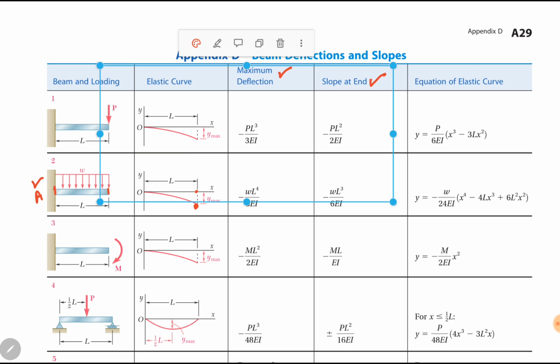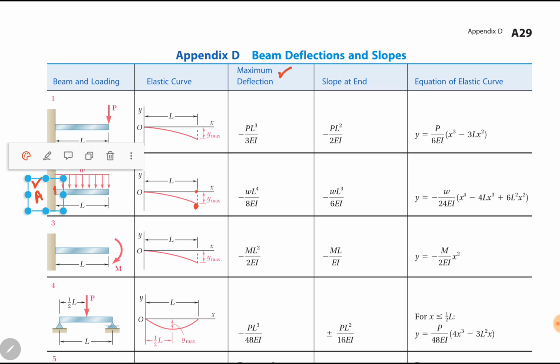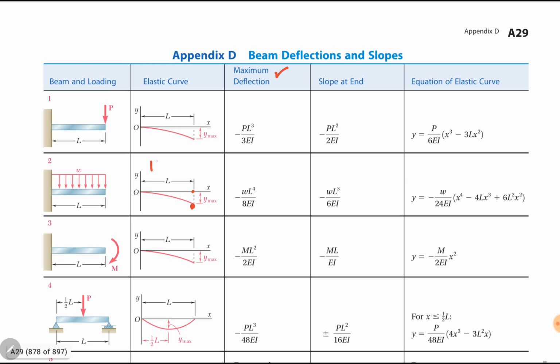Okay, I will draw a beam here of half length L by 2 and upward loading W. First remember that the given standard beam is under downward loading, but in our case loading 2, load is upward, so all the signs will be opposite.